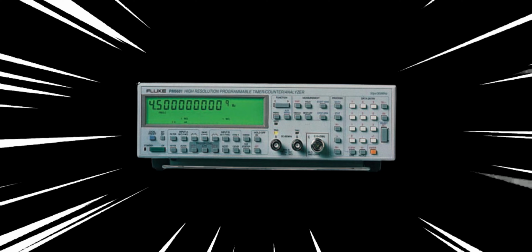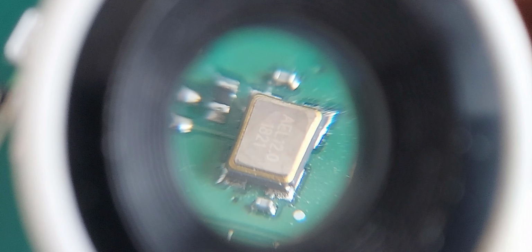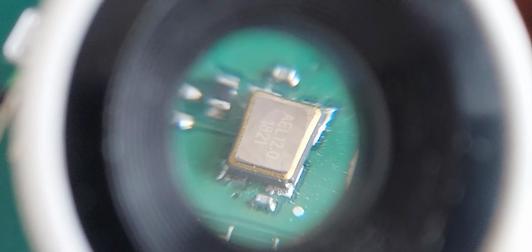In the race for more digits, the time nuts are one full digit ahead of the volt nuts. What this means for the rest of us is that even the cheapest crystal oscillator on the cheapest microcontroller board produces a relatively stable frequency with very low phase noise or jitter on the edges, which in some cases is in the single-digit picoseconds. With a single-digit millisecond PWM period, the accuracy is in the order of 1 part in 1 billion. That was the easy part.